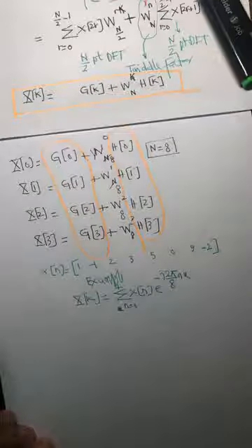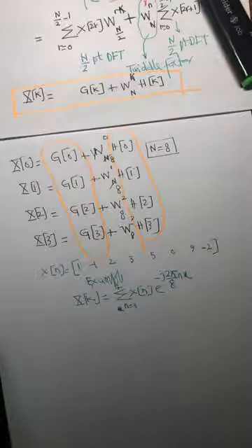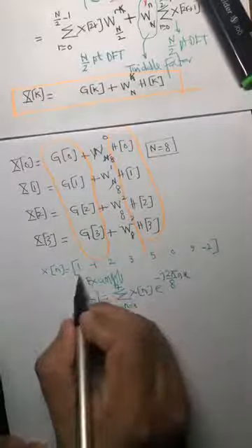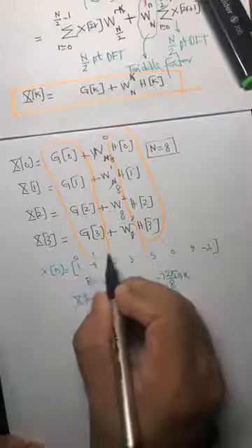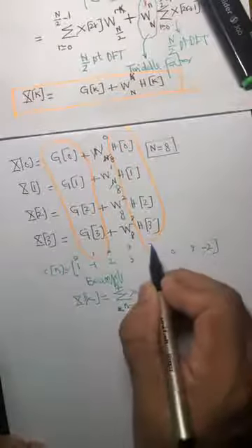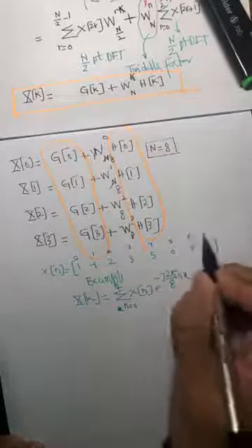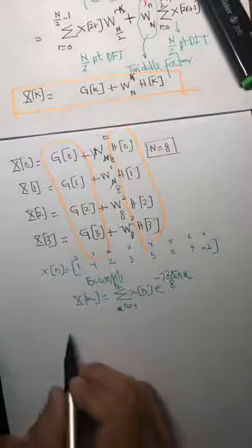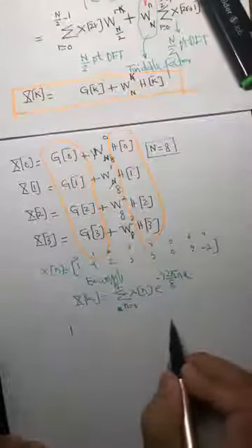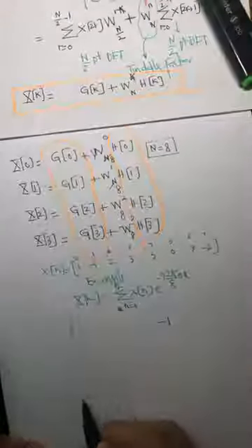The Cooley-Tukey said, let's split it into two parts. Let's split this signal into two parts. This is index 0, index 1, index 2, index 3, index 4, index 5, index 6, index 7. Keep index 0 sample here, 1, and odd index sample here, -1.